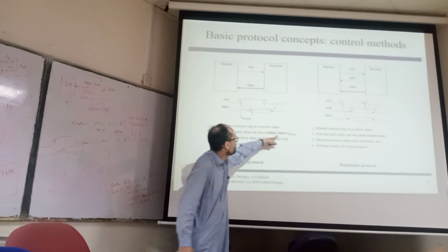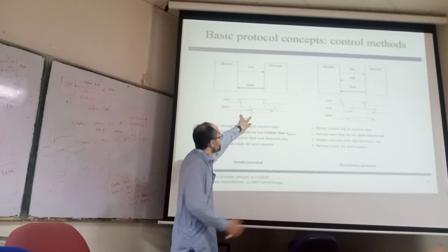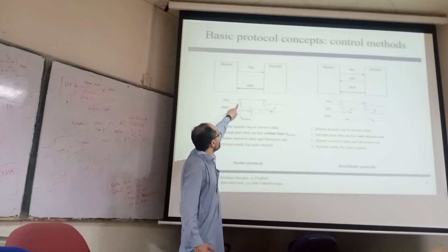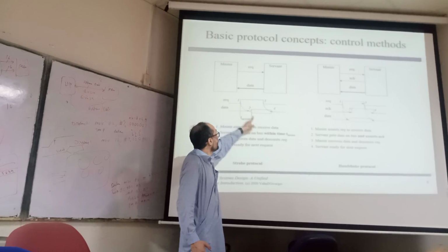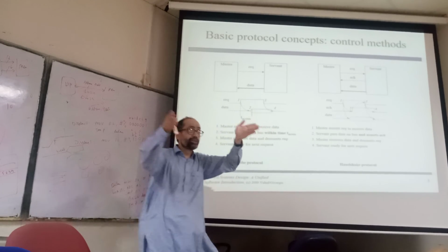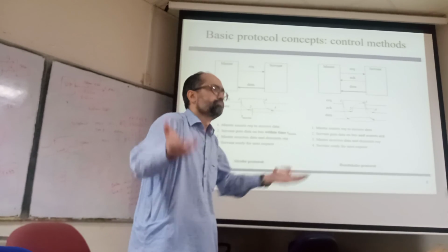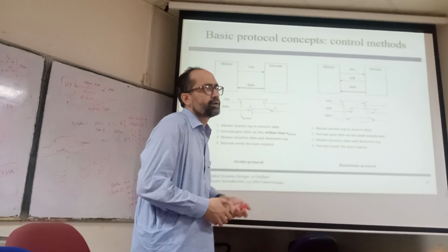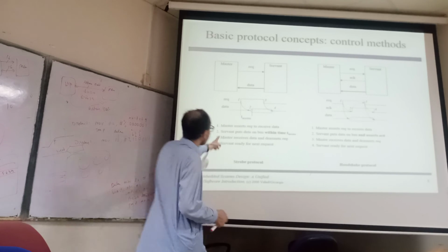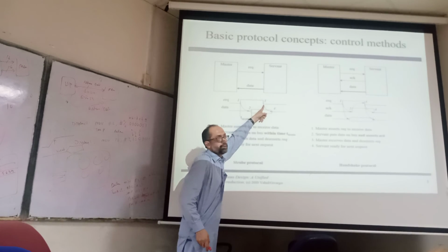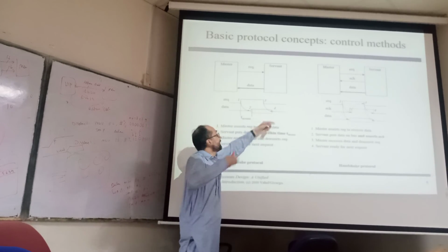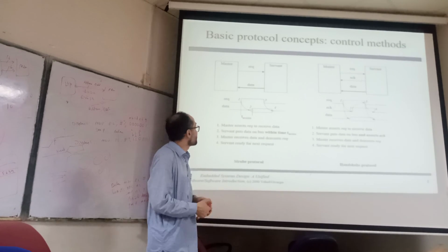The servant puts the data on the bus within time t access. This is t access, the time between the request being made and the data becoming available. The difference between these two times is called access time, or read latency. The master receives the data at point number 3, latches this data, and puts the request to low. Now the communication is done.